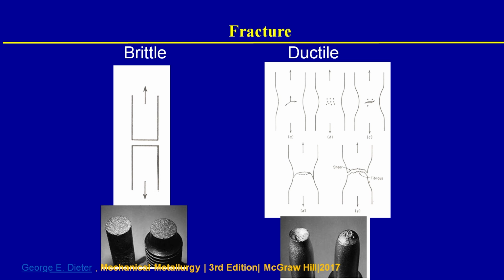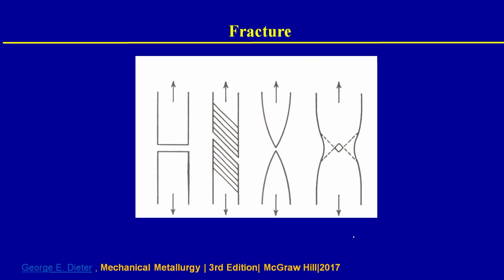This indicates the behavior of the material. Remember, fracture behavior can change depending on the temperature. Some materials may be ductile at room temperature but brittle at low temperatures, like liquid nitrogen temperatures. Many applications require you to discover materials which can be used at low temperatures, like cryogenic engines for space applications. Well, so how does it happen?